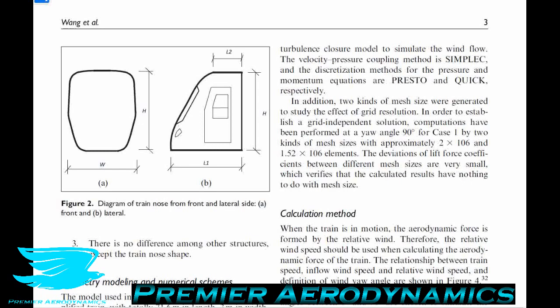But let's assume that this difference was only 0.1%, which means that the mesh is quite nice. What this also means is that potentially the mesh that they then end up using was overkill, because we don't know how few cells we need to still get the same result. They only looked at 2 different meshes, which had 1.5 million and 2 million cells. If we went down to 1.3 million, for example, do we still get a very similar lift force coefficient? So that's why we need to have 3 different mesh levels usually to begin with.